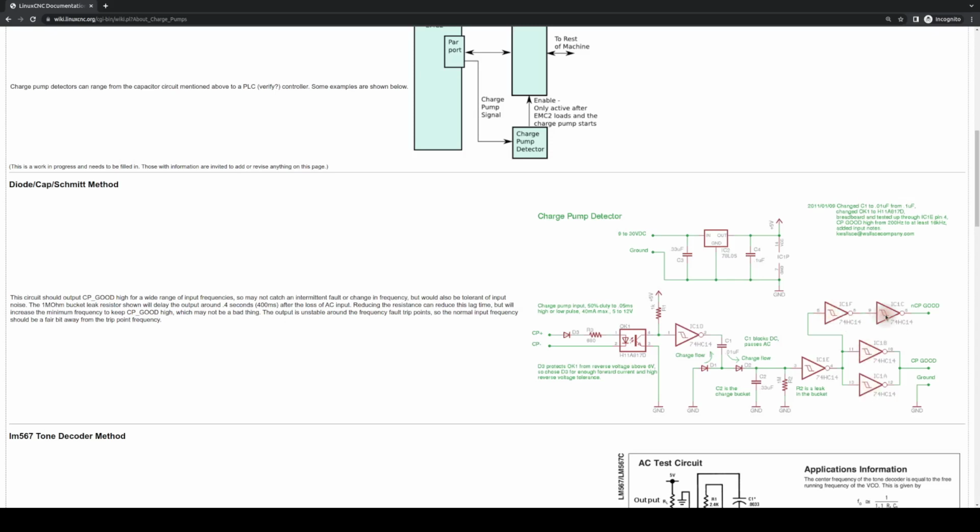I'm also not going to use an optocoupler here. I'll just use an N-channel MOSFET instead to keep the current draw on the pin minimal. Because my logic is all at 5 volts already, and I take logic power from the PC's USB port, there isn't much value in galvanically isolating the input, and all it would do is add latency.